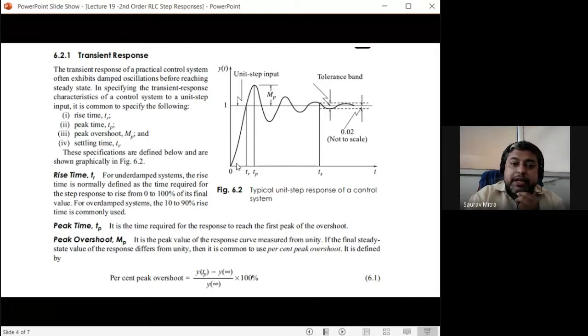Okay, so what is the output at t is equal to 0? Can you just tell me? Output at t is equal to 0 is 0. Is it observable? This is the output step response. So this dark one is the step response, and this parallel line DC is the step input. And I told you step input starts at 0 plus. So you have connected the switch at t is equal to 0, but there is a propagation delay for that wave to reach to the load and create a high 1 voltage.